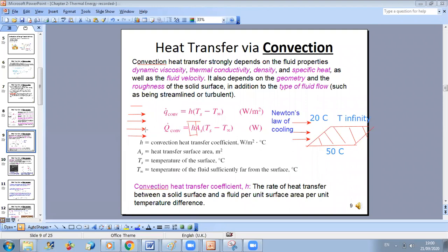On the other hand, if you increase a lot, for example, the velocity, the more you increase your velocity, the more you will have disorder in your flow. And you will start to have circulation in your flow. So you will start to see some curls in your flow, and it is disordered, it's not moving anymore along parallel lines. This is called a turbulent flow.